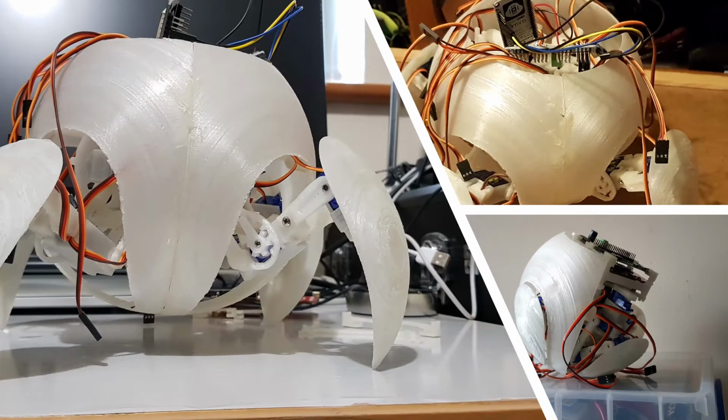Here are some photos of what I ended up building. I have made some more modifications after this, but this is the initial stages. On the left-hand picture, you can see where I used small gear adjustments on the servos. So essentially, the servo, instead of pushing or trying to turn the leg itself, was turning a smaller gear, which would then turn a larger gear. In this case, the teeth are faced inwards, just sort of inverted. That actually gave it enough strength so that it could keep itself off the floor.